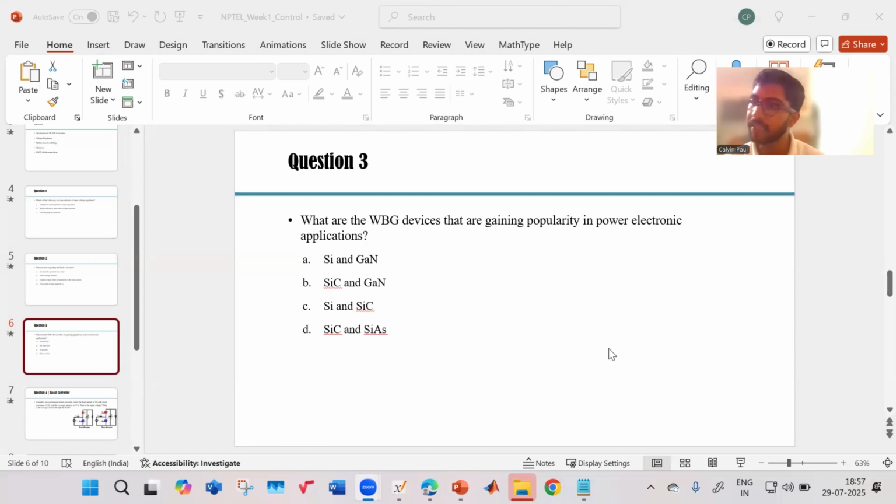And gallium nitride can switch very fast. It's possible to go to a very high switching frequency. You will learn next week, and I will also discuss, ripple: the current has a ripple, and your output voltage has a ripple. This ripple depends a lot on your switching frequency, and on the inductor and capacitor which you select.